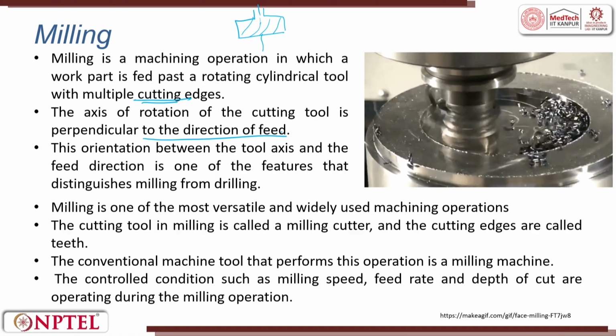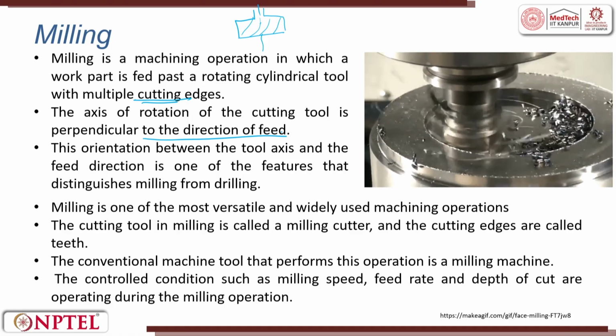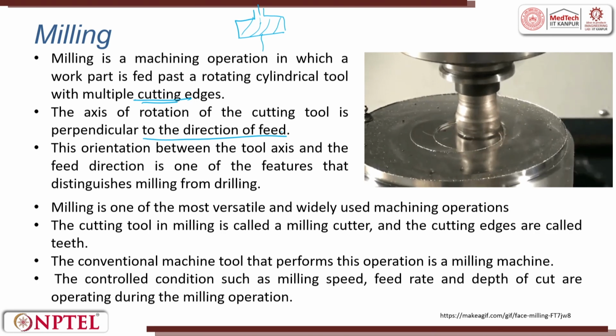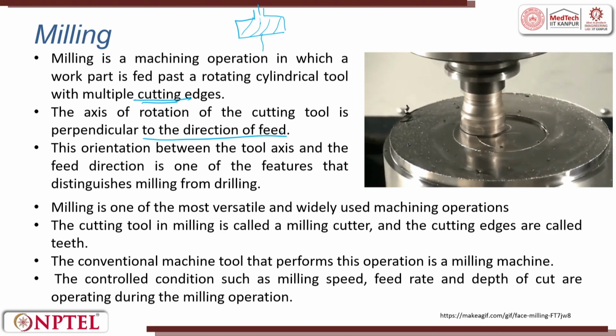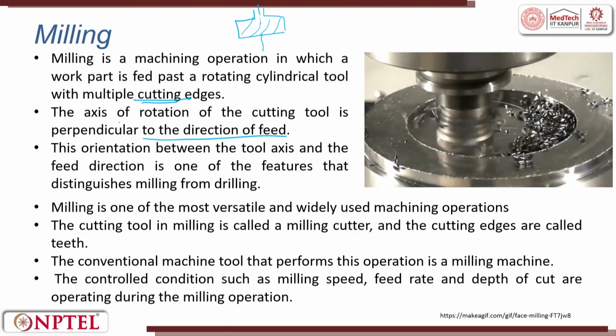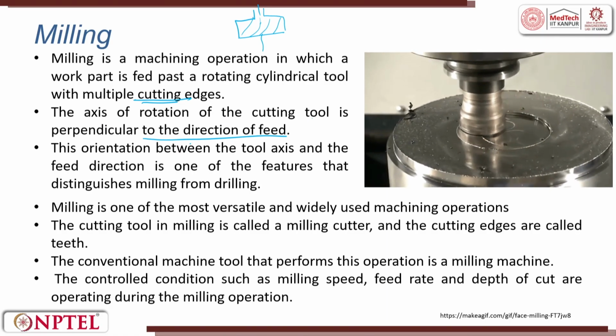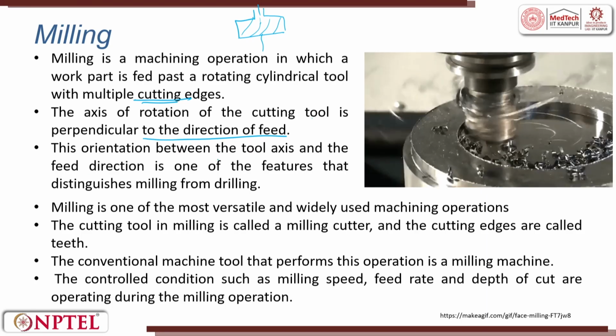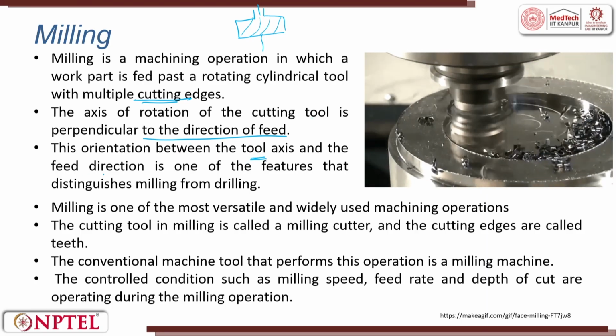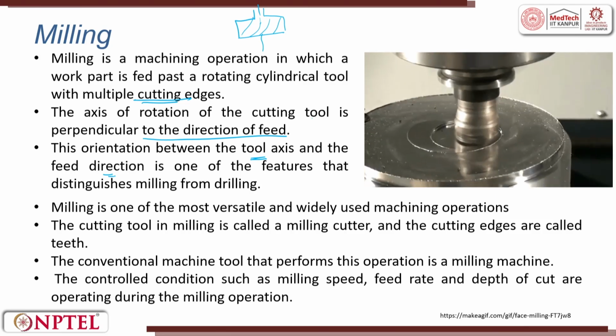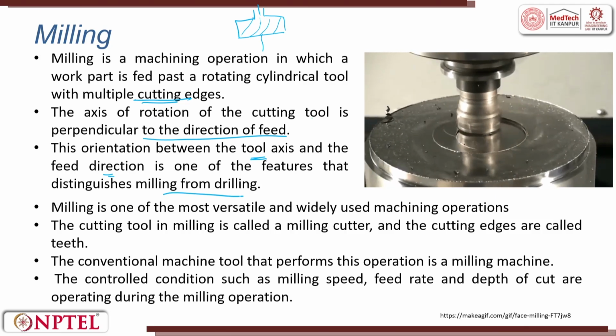This is very generic. Today you have horizontal, vertical, inclined. So, this need not be true, but the majority of the time it is true. The axis of rotation of the cutting tool is perpendicular to the direction of feed. This orientation between the tool axis and the feed direction is one of the features that distinguishes milling from drilling.